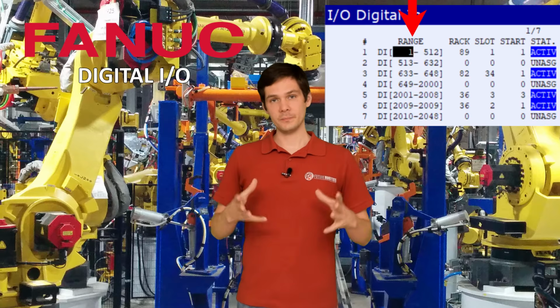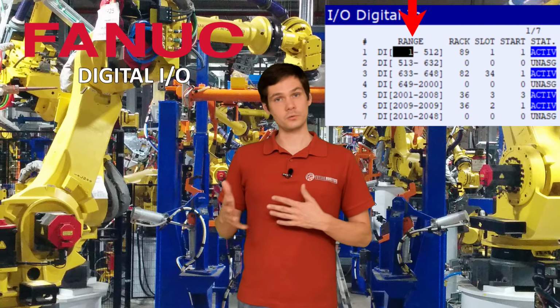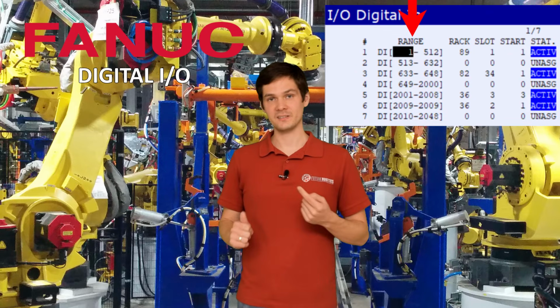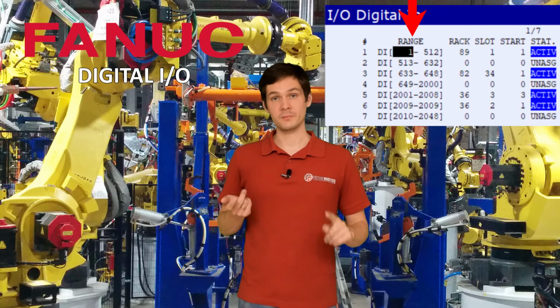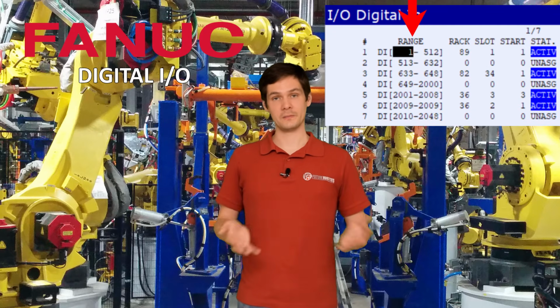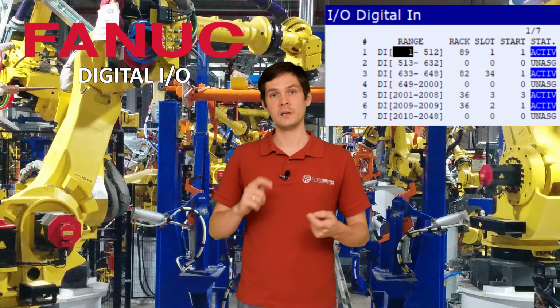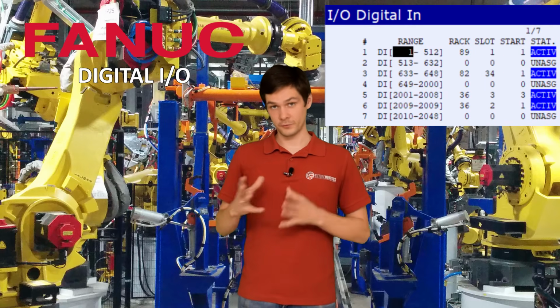Now, that means you can use 512 bits to communicate, and you can use those for whatever you want. You can send a start to the robot, you can send some information, maybe position data, whatever you want. But how do you tell the PLC that we're going to use this and this to communicate? How does the PLC know and how does the robot know? There are quite a few ways we can communicate with the PLC. Some of them are Ethernet IP, DeviceNet, or Profinet. Those are just a few.